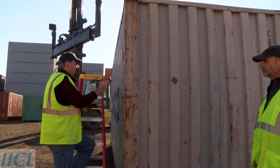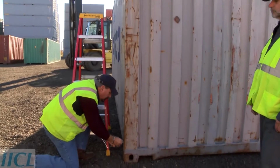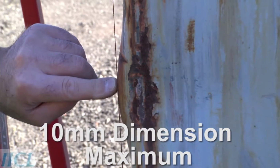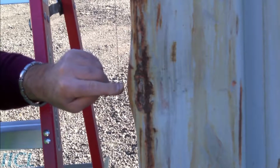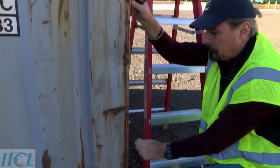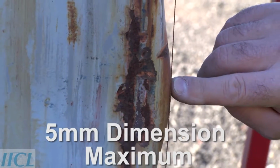In the example shown here, the inspector has used his string line and spacers to identify a plane 10 millimeters beyond the corner casting side faces. The corner casting side faces are the ISO plane for the container side, and the 10 millimeter dimension is the maximum amount that the IICL allows the corner post to bow outward beyond the ISO side plane. If any part of the corner post touches the string line, the repair is required. Note that the identical measurement method applies to the front and rear facing sides of the corner posts, except that the criterion is limited to 5 millimeters beyond the corner casting faces.